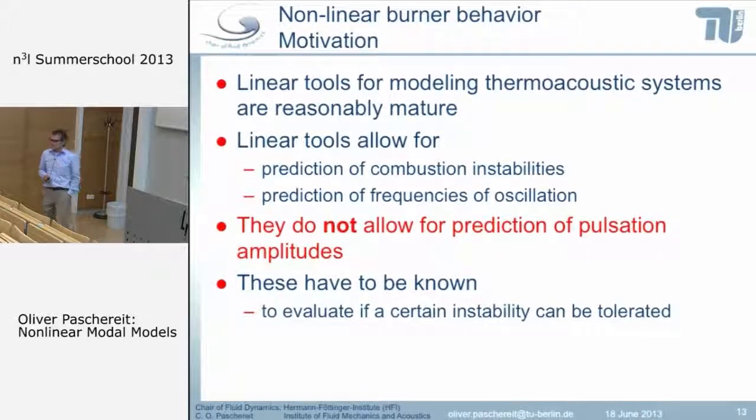The other question is nonlinearities. So if we have our linear tools, then we can predict the combustion instabilities, we can predict the frequencies, but we cannot predict amplitudes. And actually, at the end, a company is interested in predicting pressure amplitudes because that could be used as an input signal for a life cycle analysis, for high cycle fatigue analysis. If you know the excitation amplitude, you can at least try to estimate how long will your combustor live and what kind of amplitudes would you even allow.